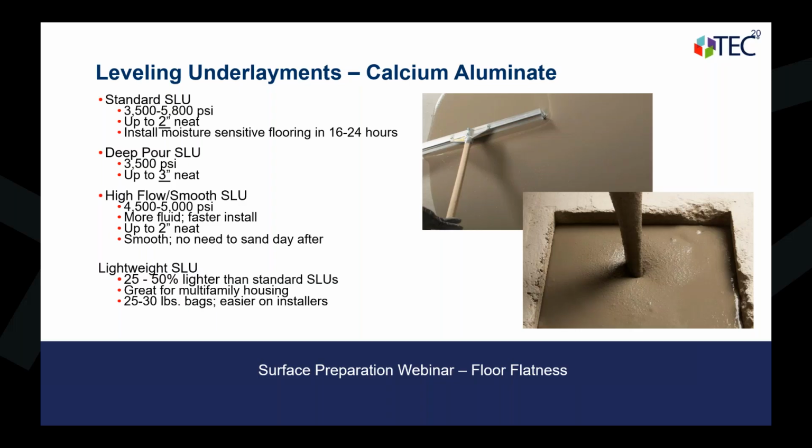And before you're installing any of the underlayments, you need to make sure you're priming. And again, it needs to be a clean, sound substrate, dry, no contaminants before you install any of these types of products.